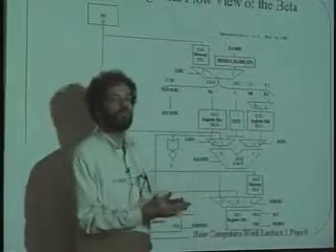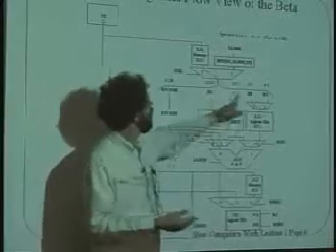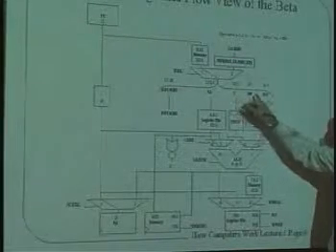And that's going to be true for those instructions which have a constant as the second argument. It also takes bits 5 through 9 and calls them register B. Now notice there's an overlap between the register B and C here, and only one of these will be used depending on whether the instruction is the type that has a constant in the middle field or a register number. And then finally the last 5 bits, bits 0 through 4, are broken off of this 32-bit word, and those are register C.